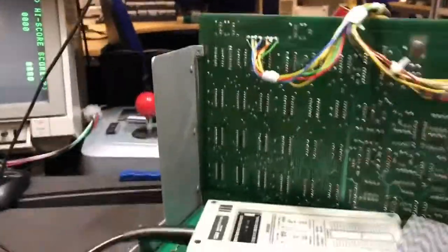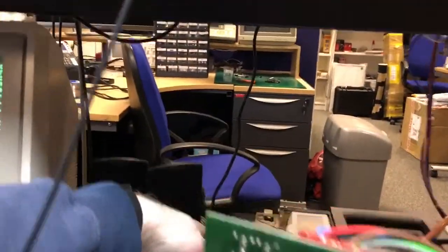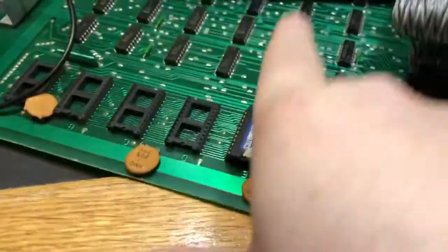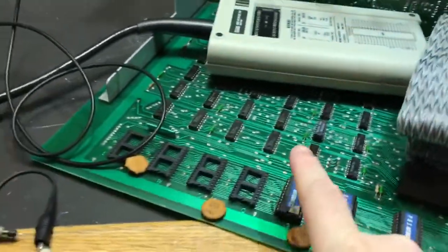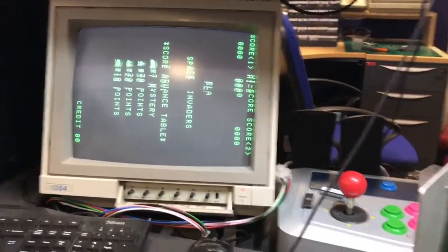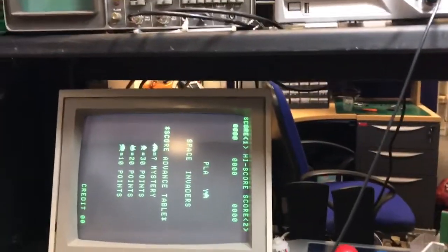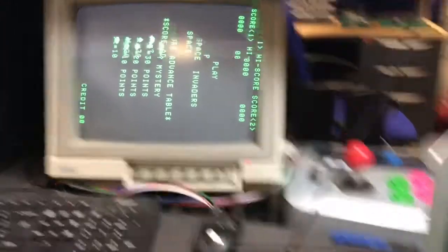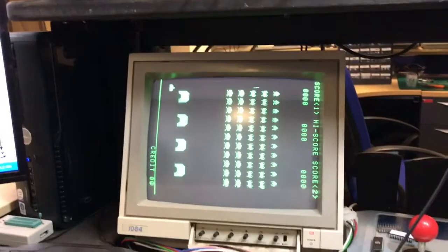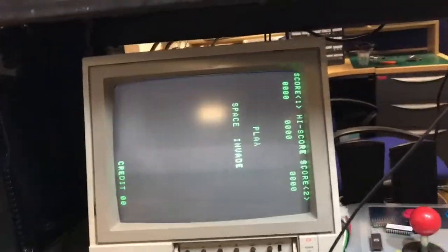We'll do some further debugging, but the main thing is the game now, at that point, is booting up. Now it might be that until I change the chip completely, that I've still got problems, and that's why it can't coin up. I'm going to test it with the scope probe and just see if it changes high-low, and then I'll change the chip, and then we'll see where we are at that point. And if we clear another coin input issue, then so be it.